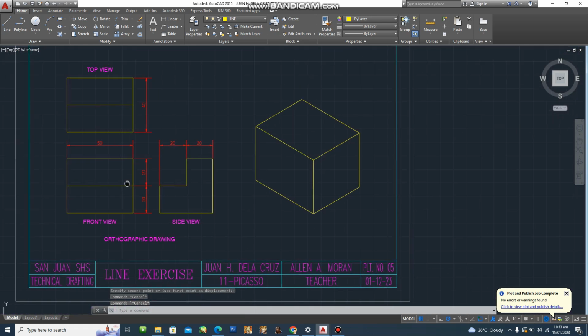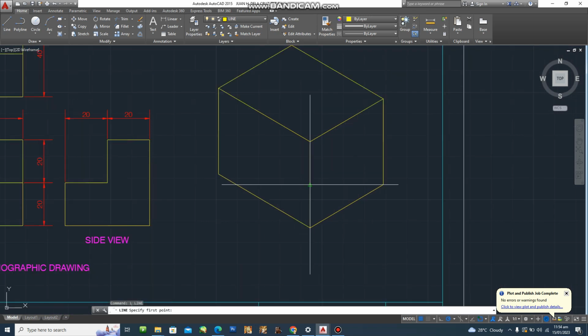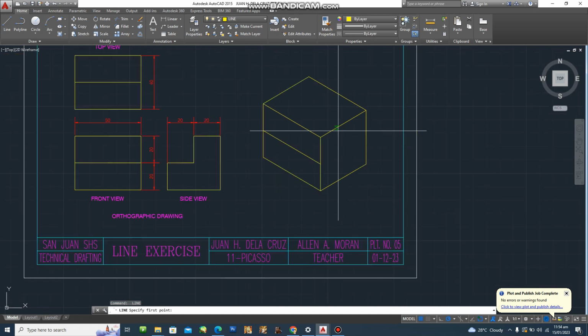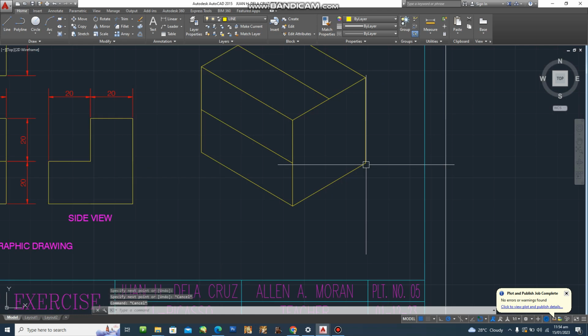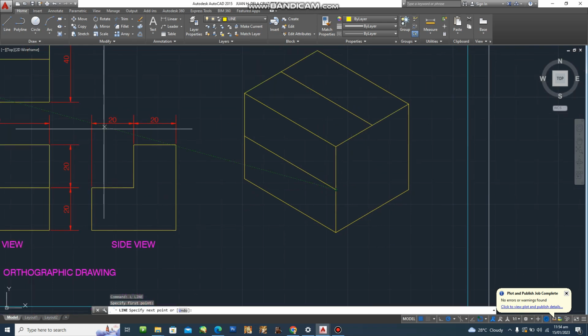For example, in the front view, in the top view, this line. You can just type N. So, situate. Ang nilitaw dito ay endpoint. Then, another endpoint. Endpoint to endpoint. Okay. Then, another type line. So, this one, there's no need for you to put measurement here. But, you can also put the specific, which is 20. Okay. Pwede naman kasi mamaya, i-bullet na lang natin. But, we just put 20 for us to avoid the fillet command. So type 20, then you just click this one.